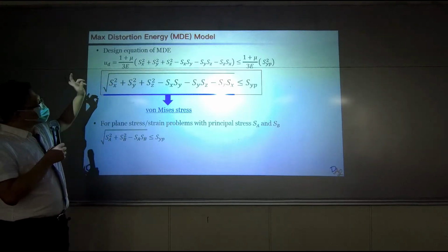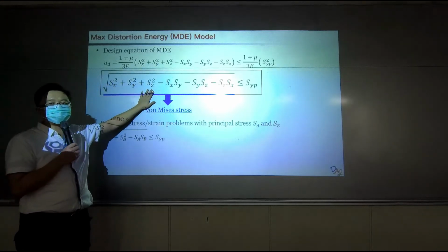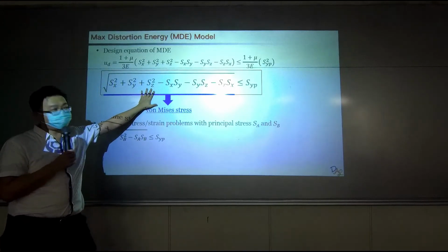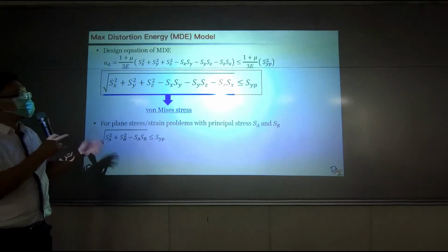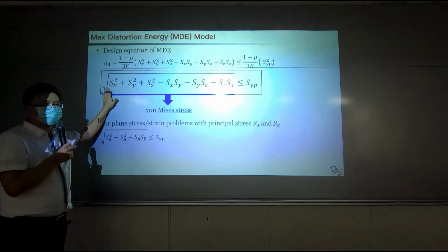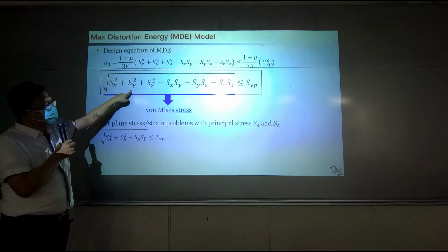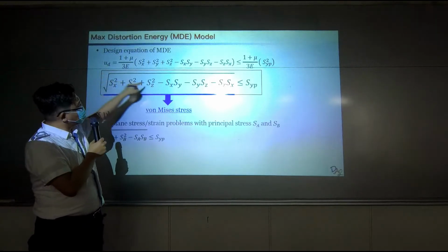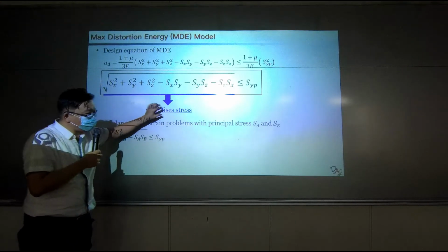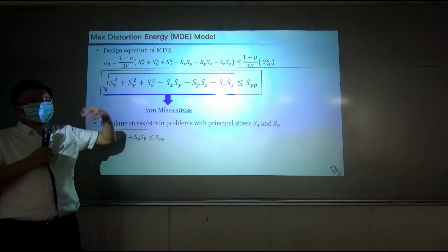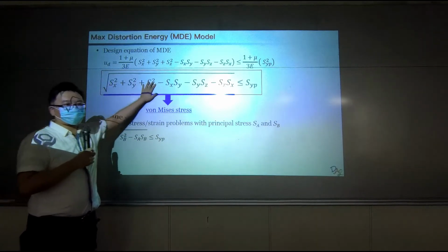And then inside the square root, we have stresses along each direction. And they are being placed together in this particular format. If the stress along x is greater, this whole term is greater. Stress in y is greater, this is greater. Stress in z is greater, this is greater. Right? So it seems like this value can represent stress levels in each direction.